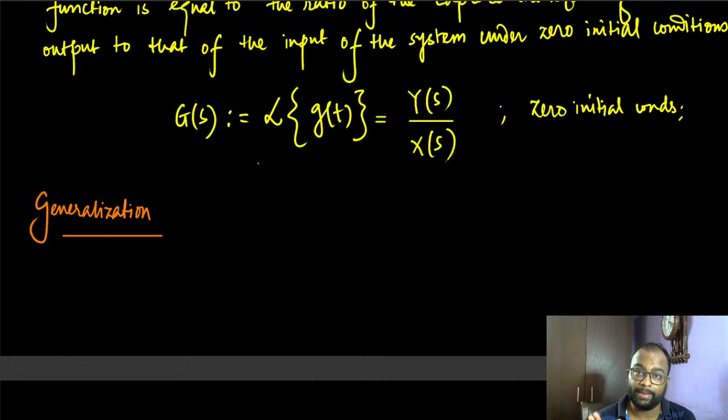Just to make it clear, we can 100% use the Laplace transform wherever we use the Fourier transform. We can absolutely do that, but since it's computationally more inefficient, we do not do that. And oftentimes all physically available signals do satisfy the Dirichlet conditions, so there won't be any question of applying the Laplace transform instead of the Fourier transform. So again, the Laplace transform is kind of an analysis tool.